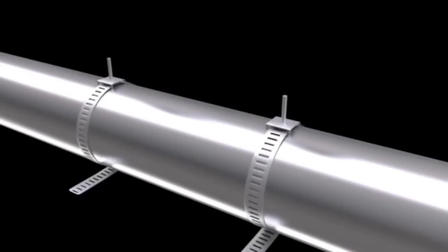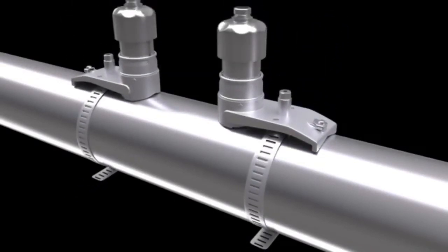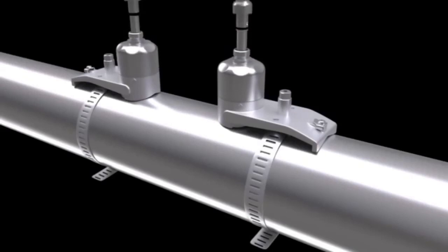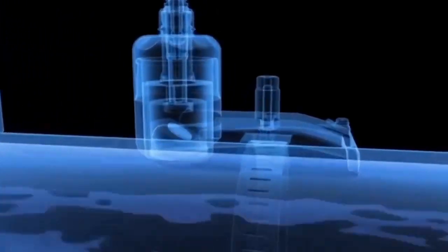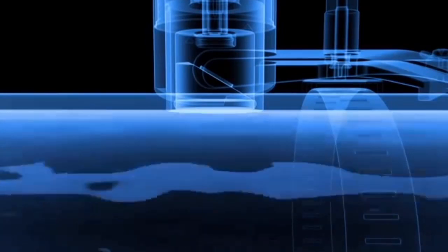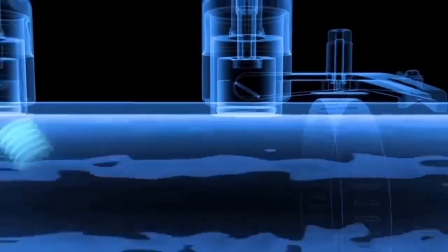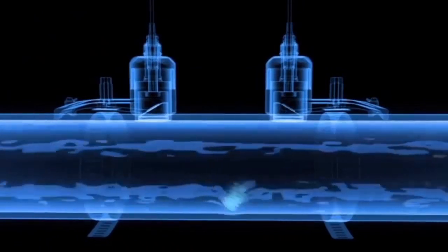For ultrasonic flow measurement, the sensors do not necessarily have to be fitted into the pipe wall. With the clamp-on system, for example, the sensors are fastened directly onto the outside of the pipe. They can be retrofitted at any time without interrupting the process. With clamp-on sensors, the ultrasonic signal is passed directly through the pipe wall and into the fluid.